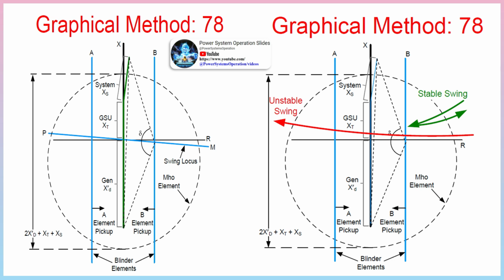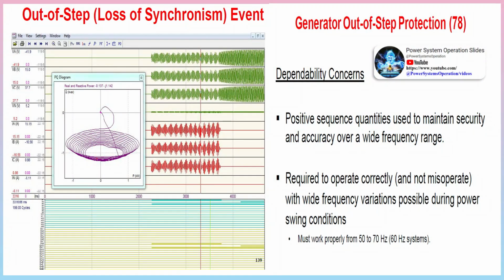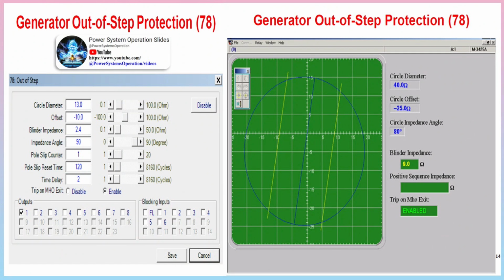Generator out-of-step protection. Types of instability: steady state, steady voltage and impedance load flow; transient, fault, where voltage and impedance change rapidly; dynamic, oscillations from AVR damping, usually low frequency. Occurs with unbalance of load and generation, short circuits that are severe and close in, loss of lines leaving the power plant raising impedance of load flow path, large losses or gains of load after system breakup. Generator accelerates or decelerates, changing the voltage angle between itself and the system. Designed to cover the situation where the electrical center of a power system disturbance passes through the GSU or the generator itself,